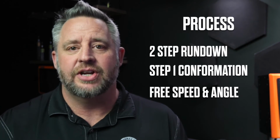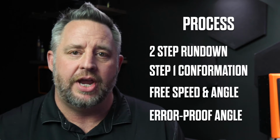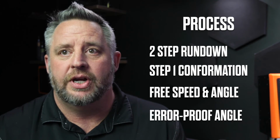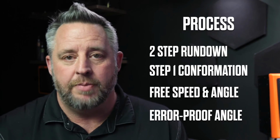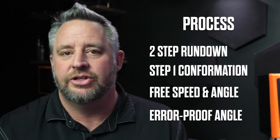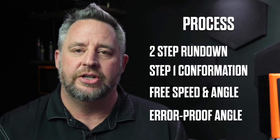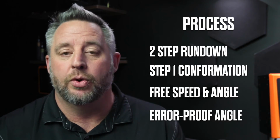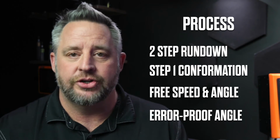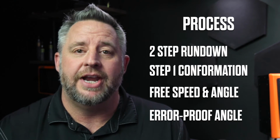In some cases, you may see operators dealing with a fine thread or other type of component where there may be some additional cross-threading or some other errors. They may start that process by hand. And so in this scenario, we're going to replicate that, but we're going to use the power tool to run down 4 fasteners just to make sure that those fasteners are started and seated.